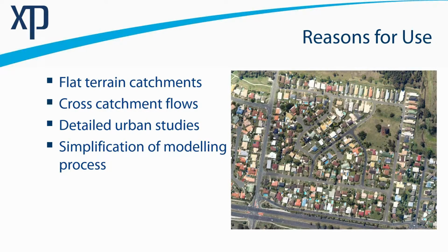Detailed urban studies. It's certainly being used a lot out here for your urban areas, because it's just very easy to apply, and you're picking up the resolution of your land use at a much finer resolution than a catchment model. You can get down to delineating buildings and roofs and gardens and roads, and with an underlying pipe system, it's a very, very powerful combination. And so in many respects it simplifies the modelling process, not from a computational point of view. Computationally we've gone up a few notches, but in terms of setting up your models, making it easier to produce these models, this is a great approach.